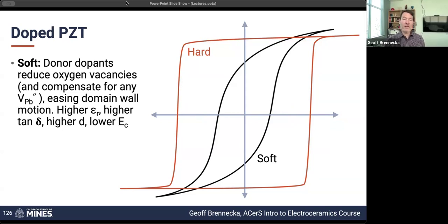Then you can also get into, as you can imagine, changing the defect chemistry, as we talked about way back in the second lecture, I think. Changing the defect chemistry also changes diffusion coefficients because you've changed the relative concentrations of oxygens versus cations and this kind of thing.